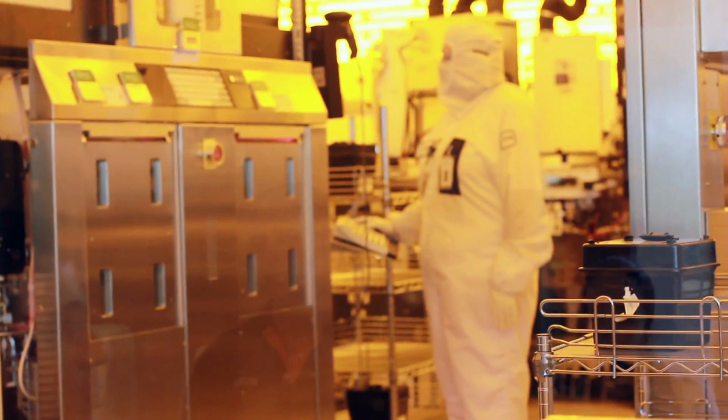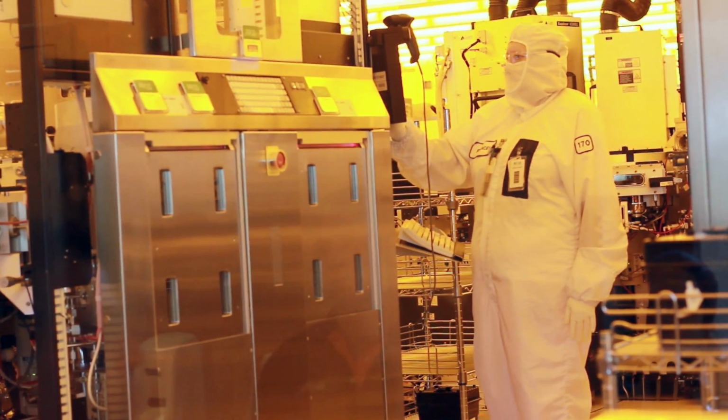The plasma area is a dry etch processing. Basically, the wafers coming from the photolithography area have the photoresist on it, but there are films that could be oxide, metal, polysilicon, or nitride, that we actually etch. We introduce gases into the plasma chamber, and the film is etched in the machine.